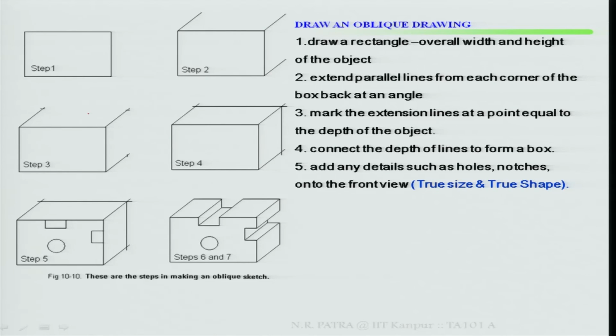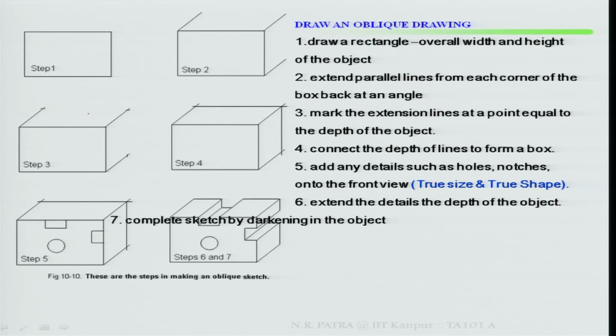Add any details such as holes and notches onto the front view. That means this is your true size and true shape in the front view. Anything that is there, add it. Extend the details in the depth direction, the depth of the object.